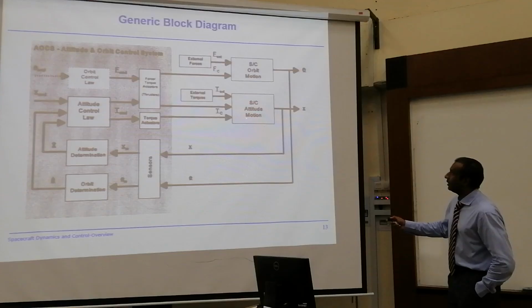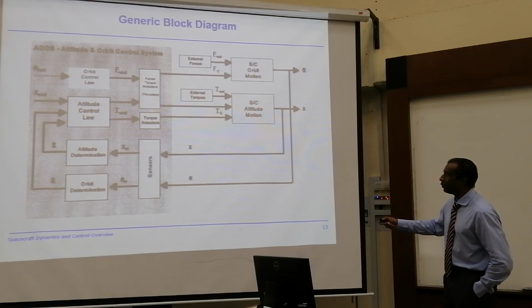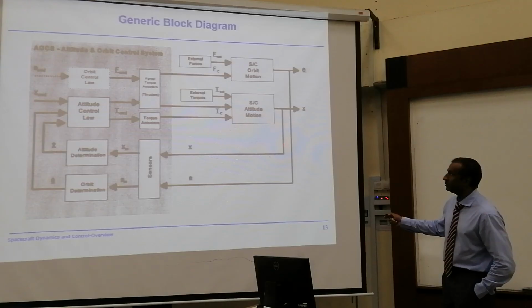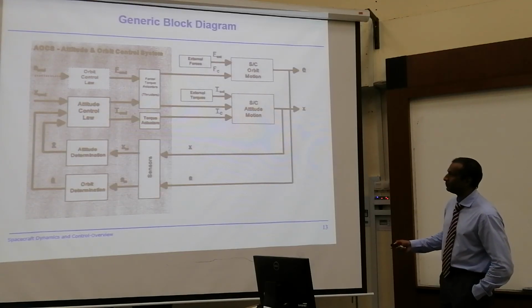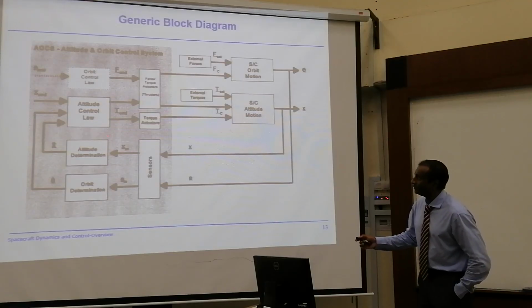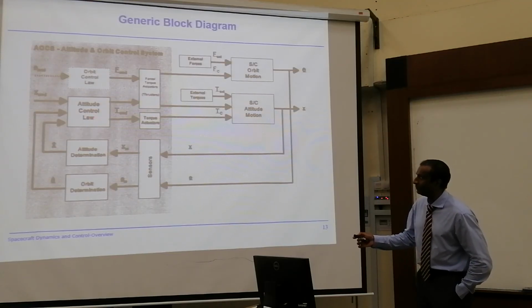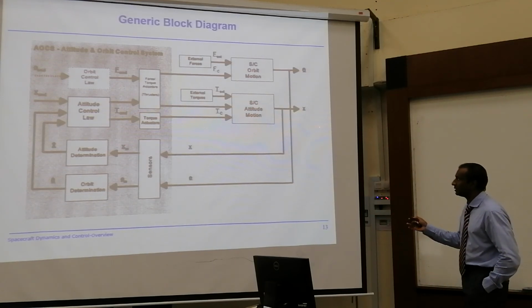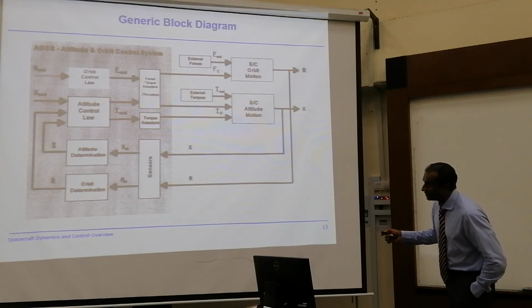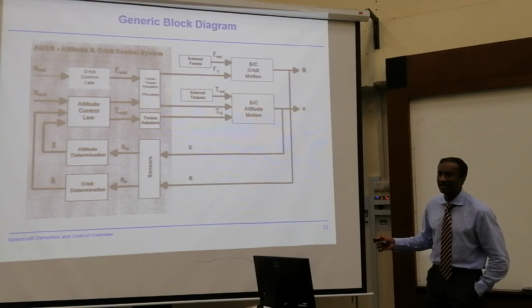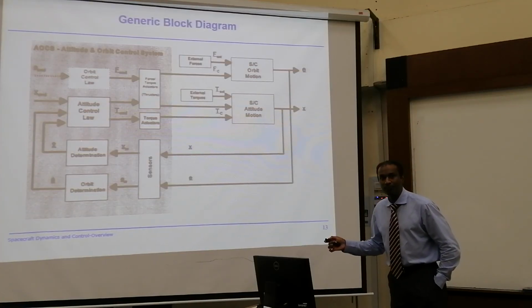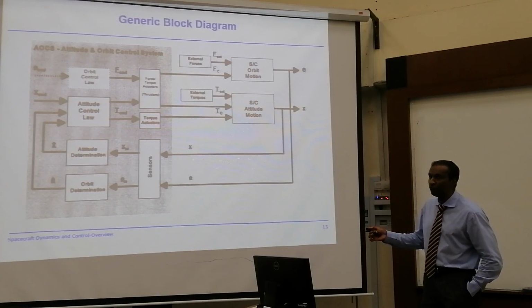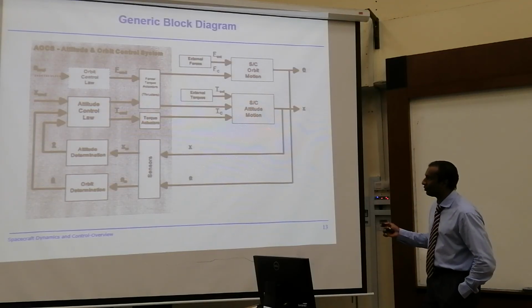Okay. All this is what you can't see. This is what happens. Okay, explain. You have an attitude control law, which is the plan, and you have the actuator. The actuator gives the actuation to the satellite. The satellite moves. Somebody detects. Who detects? The sensor detects. The sensor tells you, hey, you moved 1 degree. Again it goes to the control law. The control system again tells it, hey, move back another degree. This goes on and on and on.